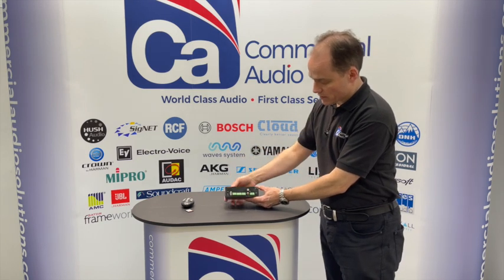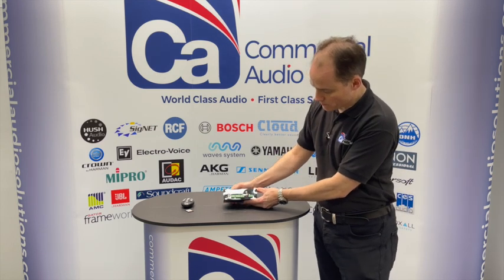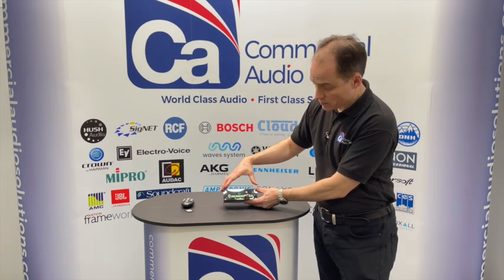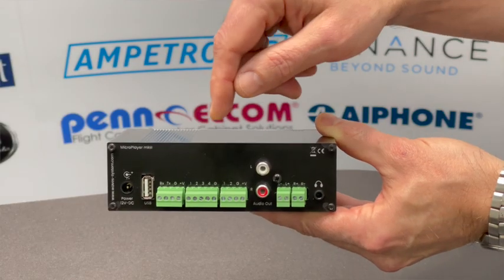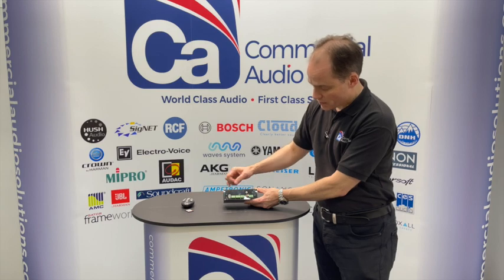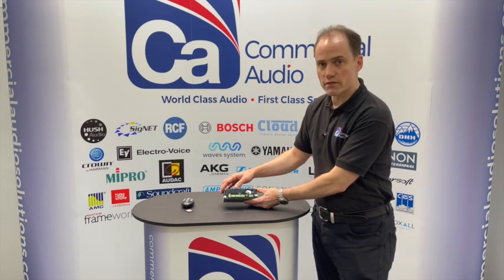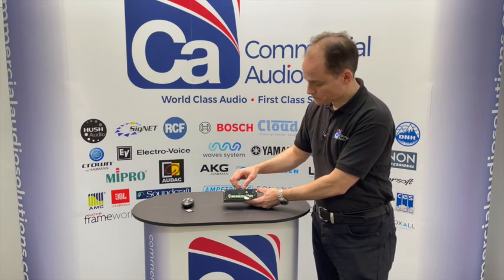Moving around the back of the player, we've got the inputs and the outputs for the player. So this player will run off RS-232, so the first set of green Phoenix connectors is the RS-232 connection. We've then got 4 contact inputs which can be used to start 4 messages. These are just 0-volt closing contacts.